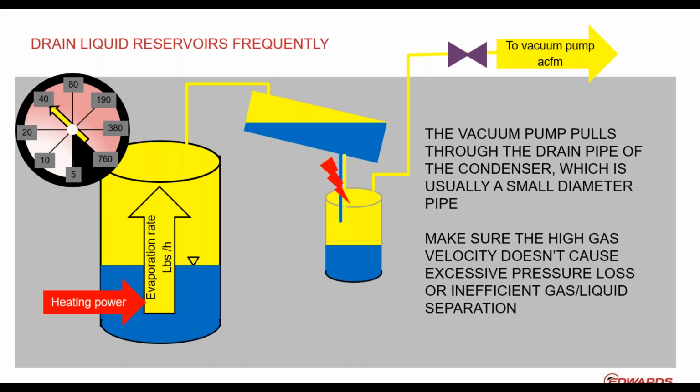the control valve on the vacuum pump is going to open when you have the set point set for the reactor. So you apply more and more capacity of the vacuum pump to that drain pipe. What happens is you just get the velocity in that 2-inch drain pipe that is too high to have a gas-liquid separation anymore. Your drain tank is partly separating liquid from gas, but you start really carrying over liquid into your vacuum pump. And I'll come back to that, why this is not a good idea.